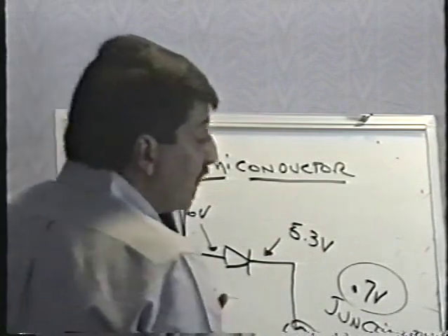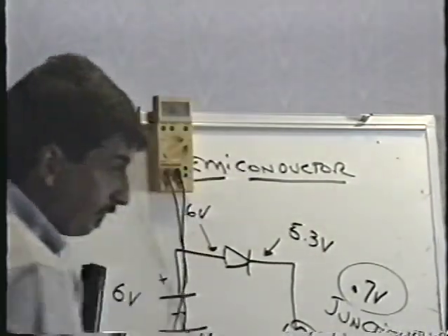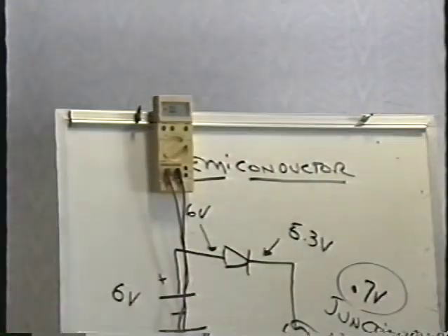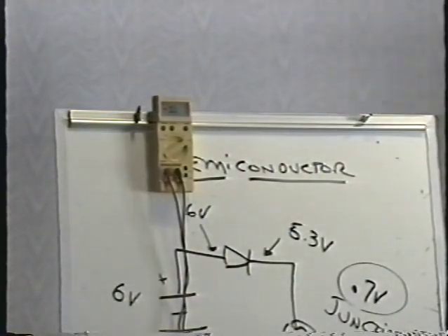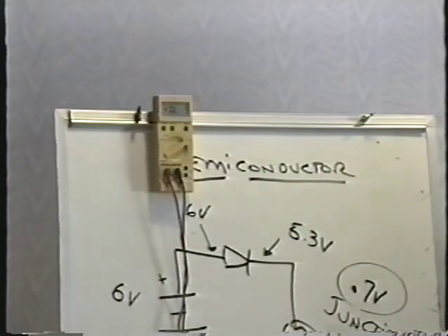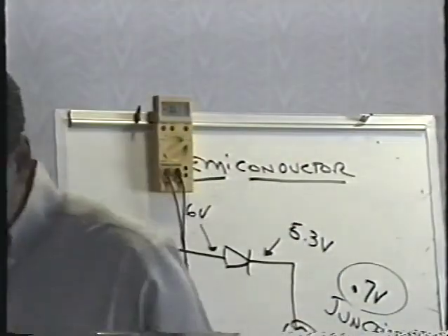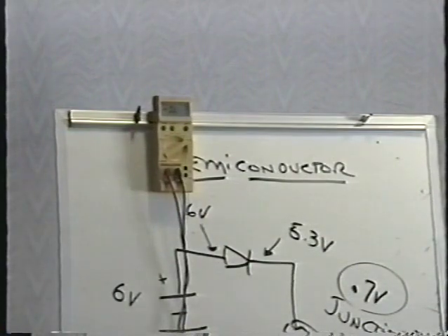Everybody try testing your diodes right now. Anybody else need a meter? Yeah. The larger one reads less. The larger one should read less.